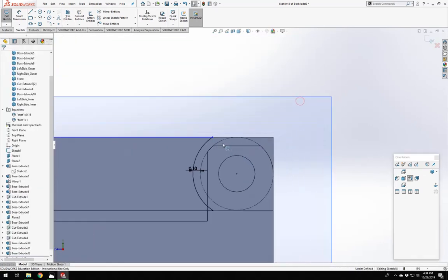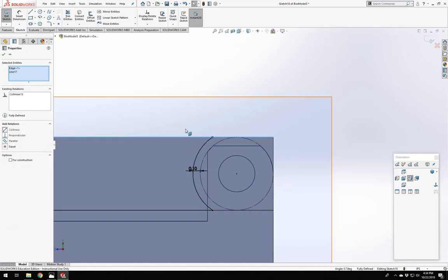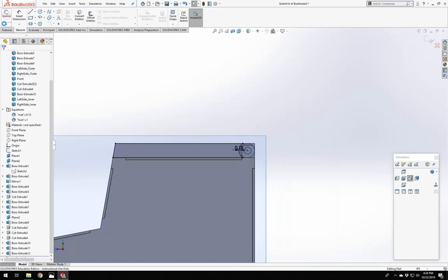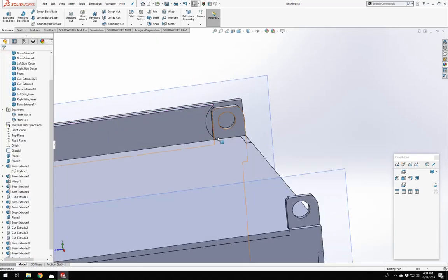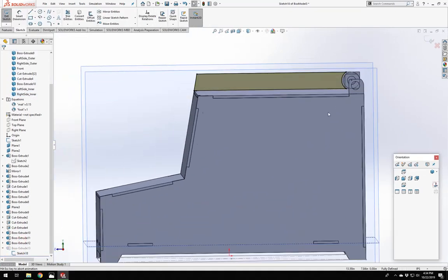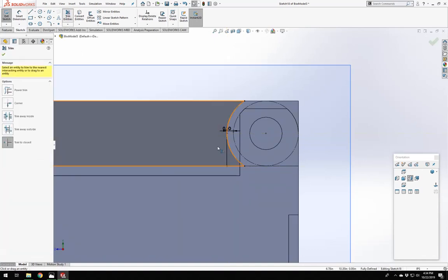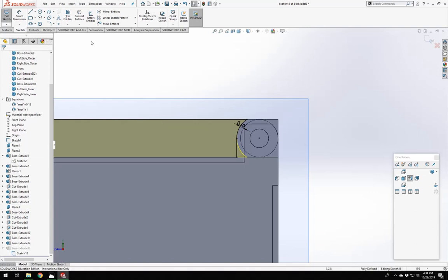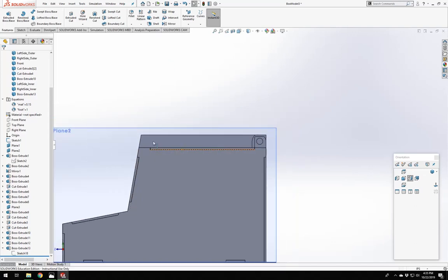This one has somehow disabled itself. Whoops. So these 2 lines just need to be coincident. There we go. So now we can extrude that. Same thing. Don't merge. So there's our middle layer. Whoops. We have a little bit of impingement there, so let's fix that. And we'll fix this so we don't have to worry about it at all. Problem solved. So that will easily clear kind of all those bits.